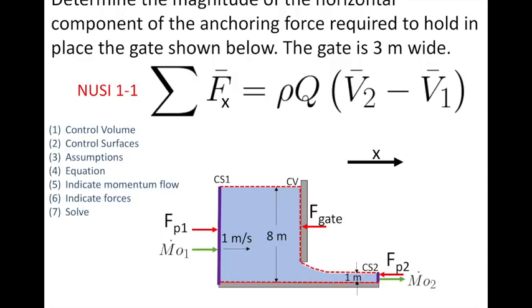Well, according to the continuity equation, we would expect that our mass flow rate at cross-section 1 and cross-section 2 is the same. Right? We're not creating mass, we're not destroying mass. How about the velocities? Well, according to the continuity equation, we would expect the velocity to increase. We've got less depth here, so a smaller area, some more velocity. So we're creating momentum in the situation, okay? Or we're adding momentum to our system, and that must be occurring because of the forces acting on our system.